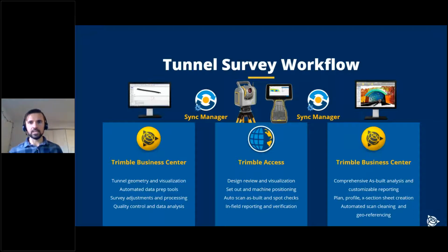So the automated scan cleanup, removing all the parasites and the noise from the scan data so I can get to the deliverable faster. And of course, the automatic georeferencing using the SX12 or SX10, where that survey workflow, we still take all of the backsite, the resection information, and it's coordinated with the scan. So if I have to update my control information, that scan data moves with my control. So really building that confidence on all of the data in one environment. So that's looking at the workflow from a high level.